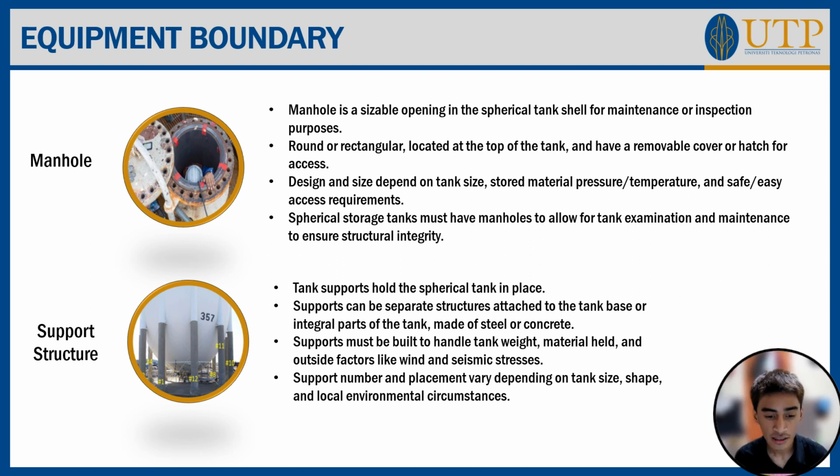And lastly, the support structure. The support structure's purpose is to hold the spherical tank in place. The support can be a separate structure attached to the tank base or integral parts of the tank made out of concrete. The support must be built to handle the tank weight, material weight, and also outside factors like wind and seismic stresses. And the support number and placement vary depending on tank size, shape, and local environmental circumstances.